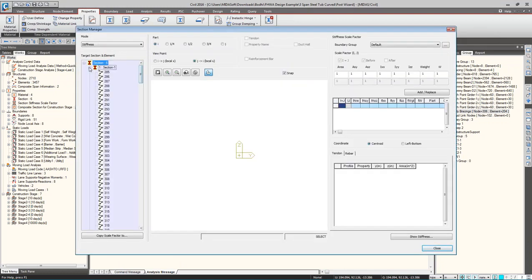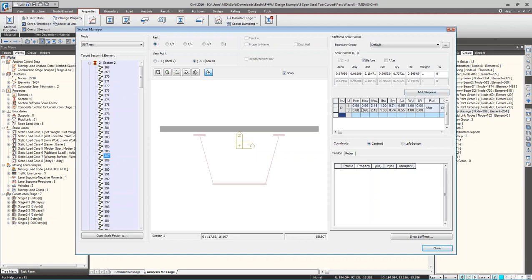Okay, so inside each and every section you will get the sections that are there. If it's for the steel section, what you can do is go to a particular element, and then you can give your reinforcement scale factors in here according to what you want for the corroded section. This is something you have to go to default, of course, and this is something that you include in the corrosion. You have to decrease the stiffness of the section where there is a corroded section, right? If you wish to model the corrosion, then you have to go for plate elements and do the model.